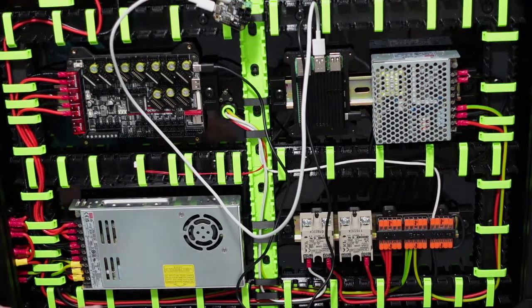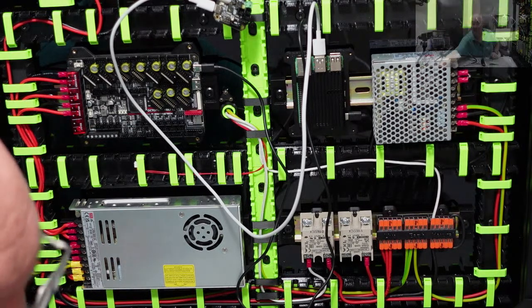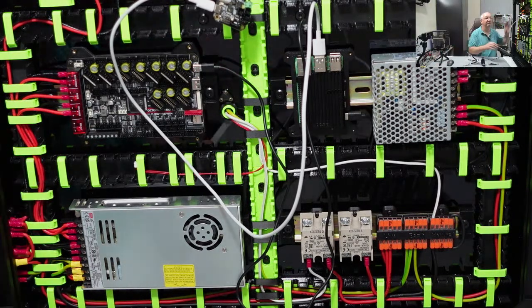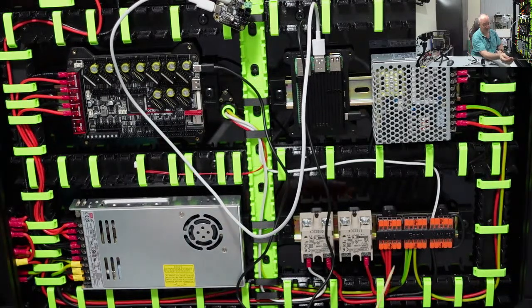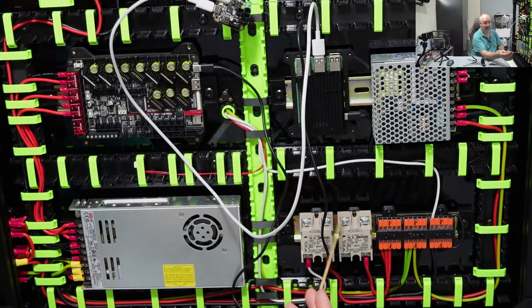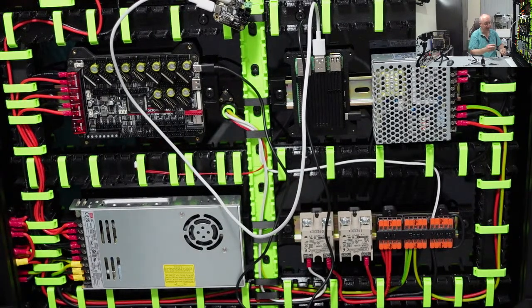So I did tests on the frame all over the show, just to see if the frame actually connects everywhere. And yes, it's connected everywhere. So it doesn't matter where I take my meter and plug it in, I can test it. I've got continuity. So I can take any point on the actual printer frame, but I'm going to take a bit of the paint off and actually make sure I get a very good earthing on it.